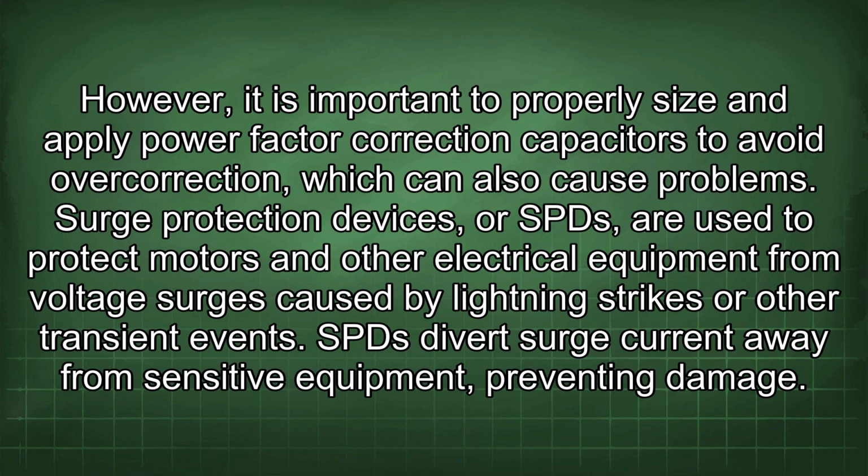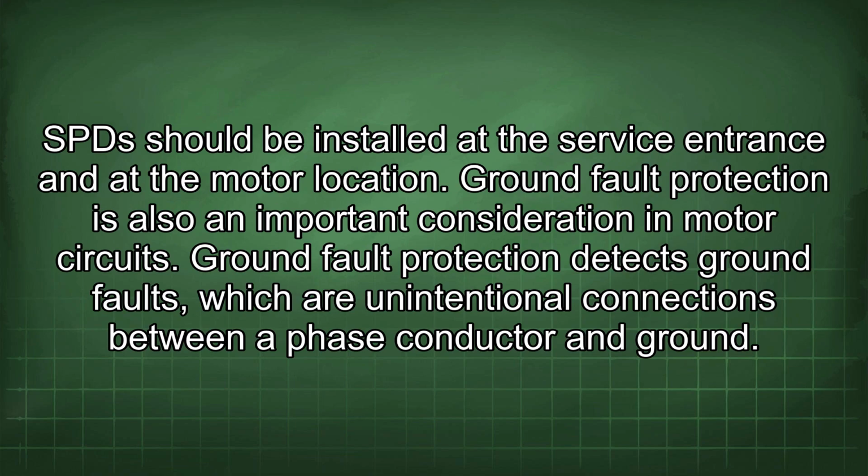problems. Surge protection devices, or SPDs, are used to protect motors and other electrical equipment from voltage surges caused by lightning strikes or other transient events. SPDs divert surge current away from sensitive equipment, preventing damage. SPDs should be installed at the service entrance and at the motor location.